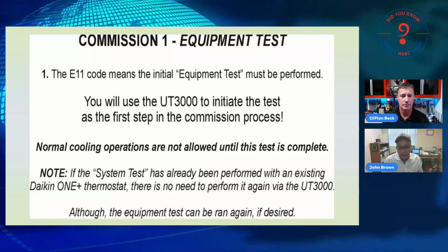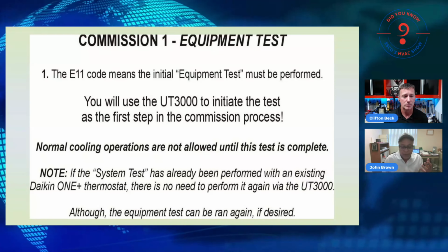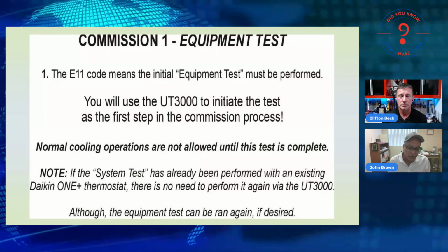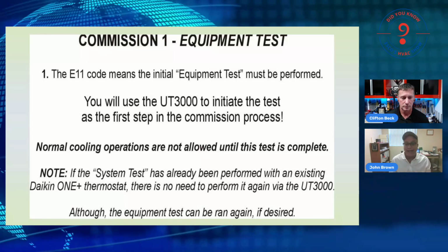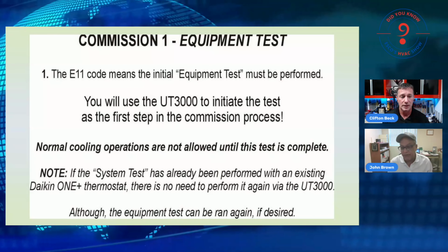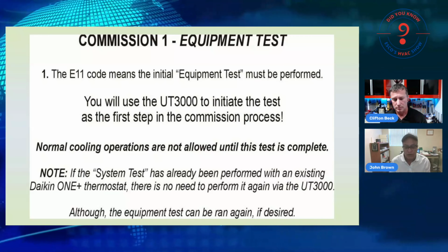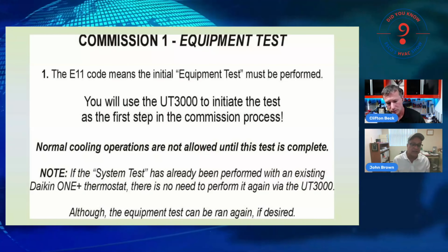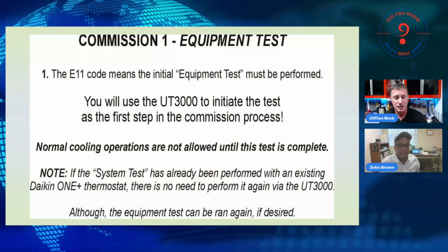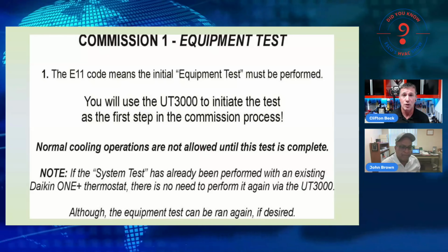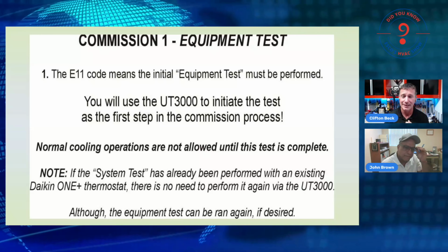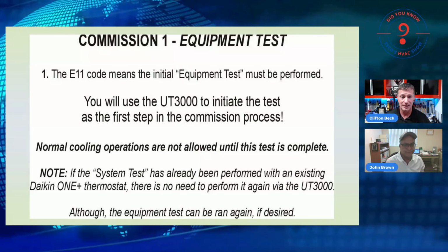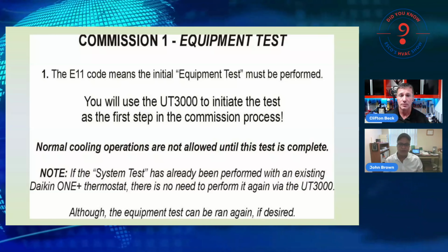And this is one really important logical reason why we decided to encourage use of the zone controller rather than the thermostats, because we can guarantee all the dampers are open. Some of them not being closed could affect the outcome of your system test or your charging mode. Just imagine if a system itself is trying to ramp up to 100% capacity and it has dampers closed. What's that going to do to the load on the evaporator? Definitely not going to get a correct reading.